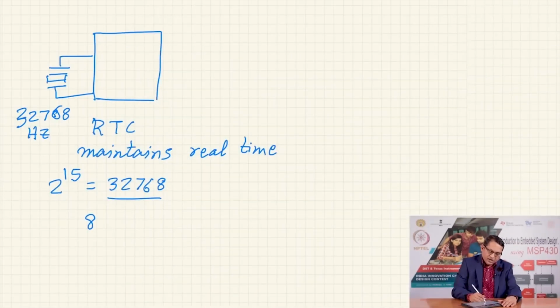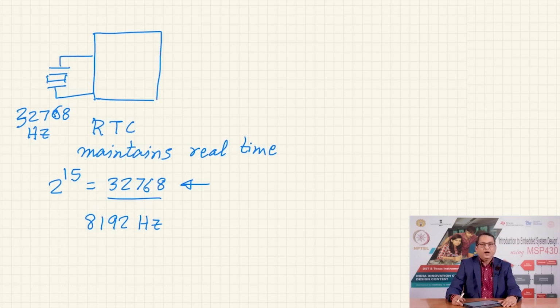It is small enough in size, and it would lead to relatively less power dissipation. Although for the record I may mention here that the very first digital quartz crystal based clock that came on the market was a Seiko clock, and it actually used an 8192 Hertz crystal. But subsequently the common frequency of use was this, and this frequency has since been adapted and adopted for use with RTC chips. Usually this is an 8 or 16 pin IC.